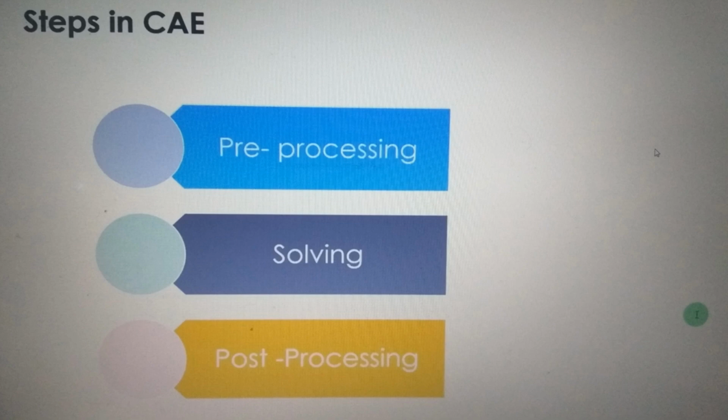You might be wondering, when I told you that I'm going to introduce a bead in the middle of the L bracket, how can I tell that? This is a very basic example when you work on optimizations, and it is based on my experience. An L bracket under heavy load will fail at the region where the bend happens. The failure will be initiated there. So if you stiffen the bracket there, it is going to give you much better results, right?